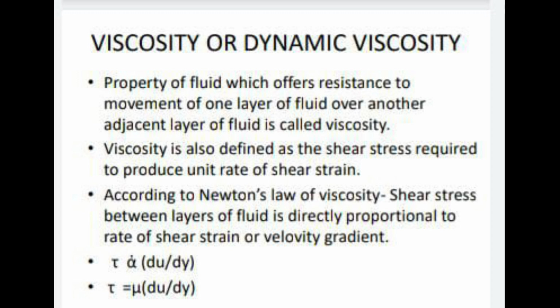So this property of fluid, which offers resistance to the movement of one layer of fluid over another adjacent layer of fluid, is called viscosity or simply dynamic viscosity. Viscosity is also defined as the shear stress required to produce unit rate of shear strain.